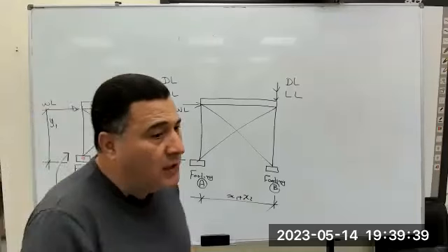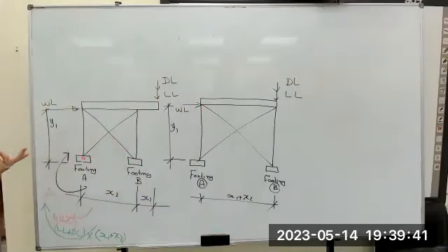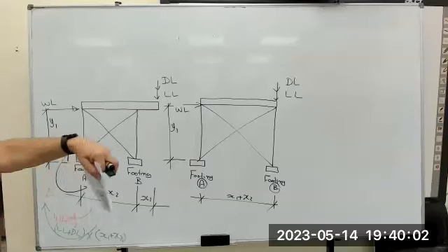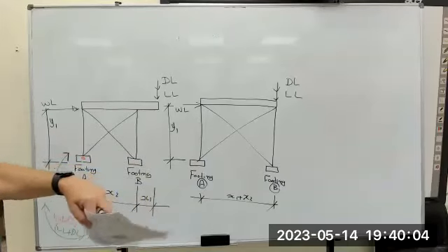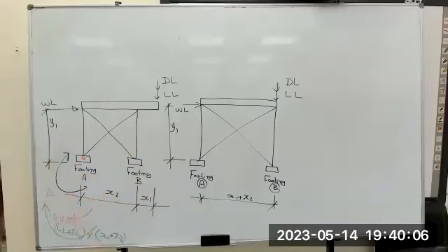What will be reduced is the uplift on the foundation. To reduce the uplift, what do you have to do? I will increase the foundation. Number one, the foundation itself, increase footing B, make it very big, heavy. Correct or not?